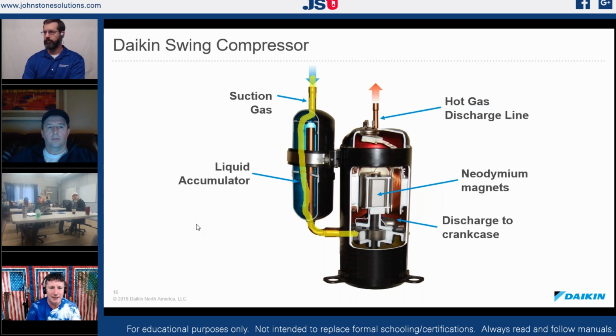So I started looking at it from the perspective of why. Well, if we look at construction, it all goes back to why we are all here. If we understand the construction of something, we can better diagnose it. So we simply started looking at that and went, man, if we open the suction valve first, which people have been taught in the past in Goodman installation manuals, then we would literally pull the oil out of the compressor and we would have a dry bearing on startup.